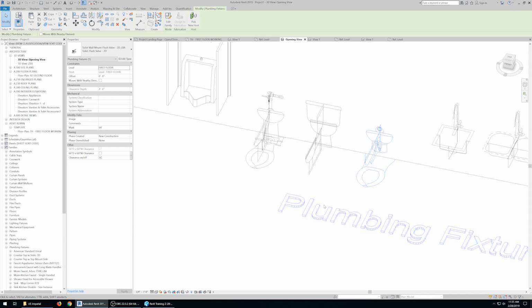So that's another thing that we're trying to iron out the wrinkles, because what we're trying to do is as we create new families, we want to start from the same kind of start point. Where that is sometimes, where to find it is you export that file to a CAD file and find where 0, 0 is. Measure that distance from 0, 0 back to a corner known point, and then go back to your family and move that to the right spot. Sounds like an antiquated way to find where the origin is, but what I found is if you have a family that works, open that family.